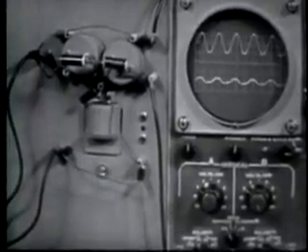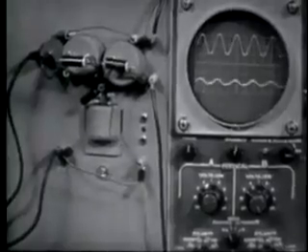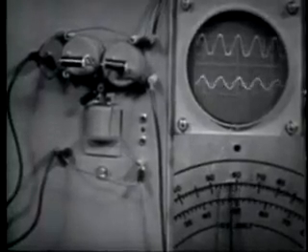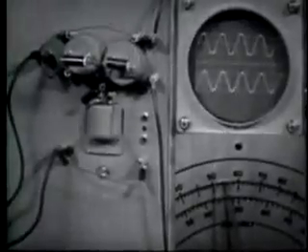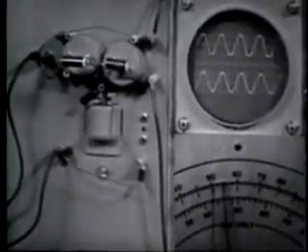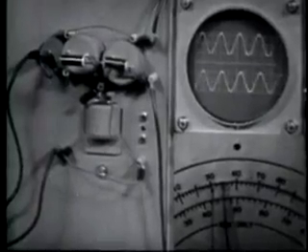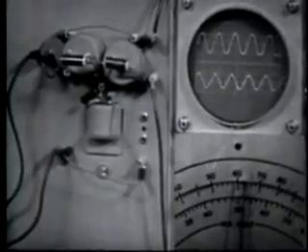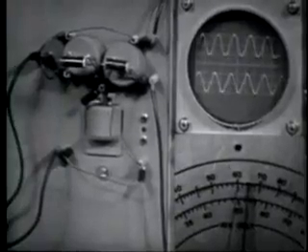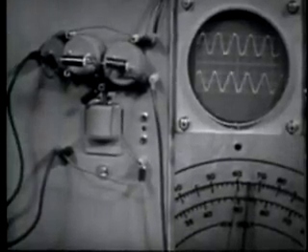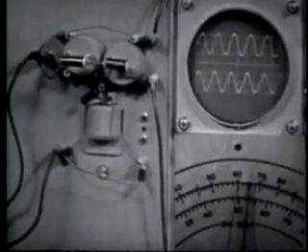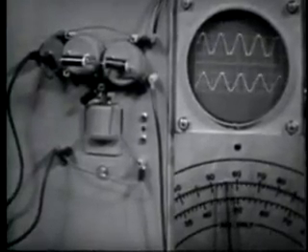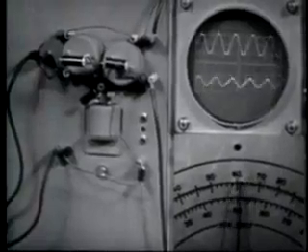Now let's check the frequency response of this circuit and see if we have indeed improved it. All right. Notice now that I only have to go down to about 550 hertz, and I have maximum output from the filter. The same is true on the other side of the frequency we wish to reject. At about 650 hertz, I now have maximum output from the filter. So I'm now rejecting a band of frequencies much closer to 600 hertz.